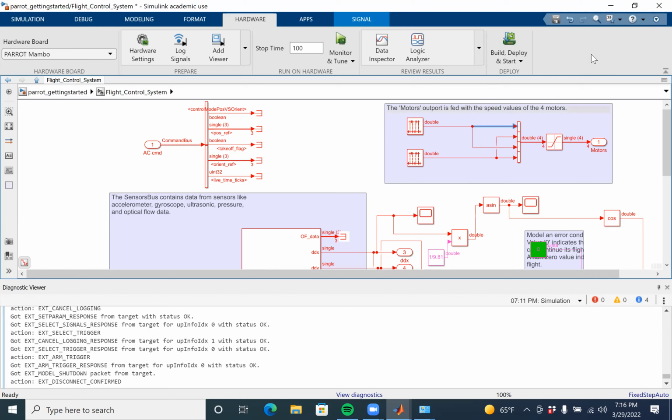Then what is that E theta? That is the error angle: current angle minus set angle. Current angle is the angle that you get from the complementary filter. And set angle is when the aircraft is horizontal, the roll is 0, pitch is 0, set angle is 0.